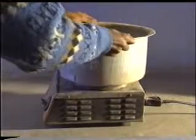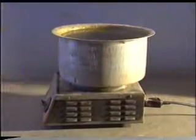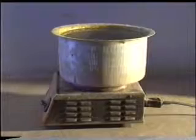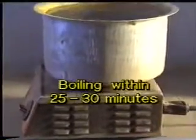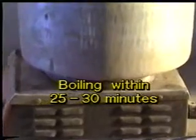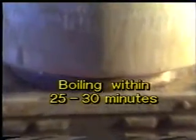At the end of 24 hours, heat the water with assembly submerged at a rate so that it starts boiling within 25 to 30 minutes. This is done to accelerate the slaking of magnesia with water.